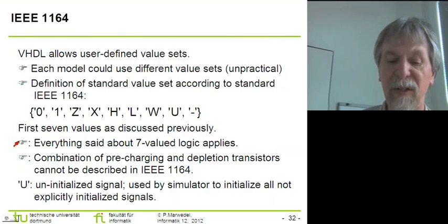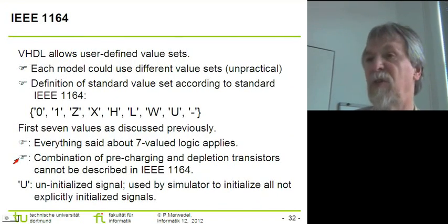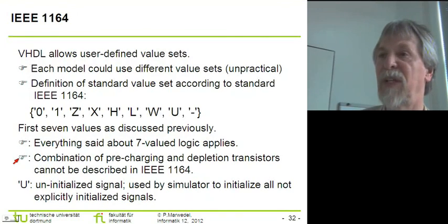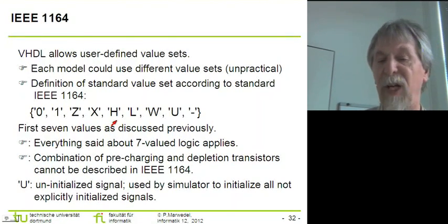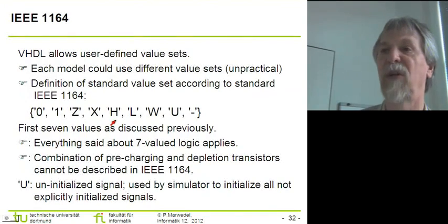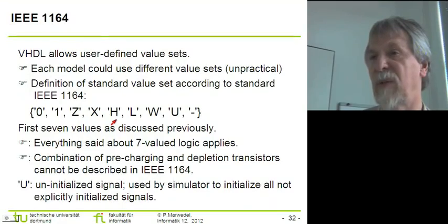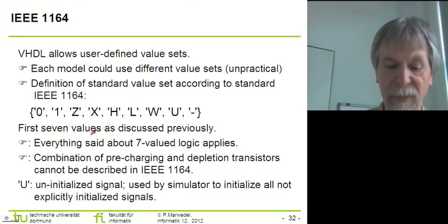So everything that I said about these 3 logic values applies, which means that we cannot really describe a combination of pre-charging and depletion transistors in IEEE 1164. We could possibly abuse these values to describe pre-charging, but then we can't really use these values for describing depletion transistors. There is only one set of weak values.